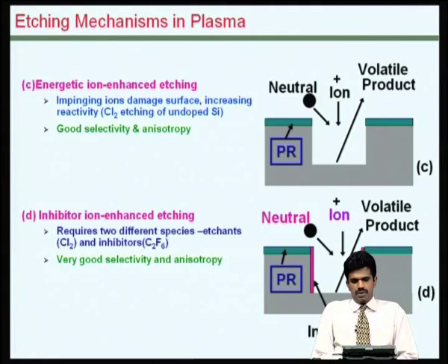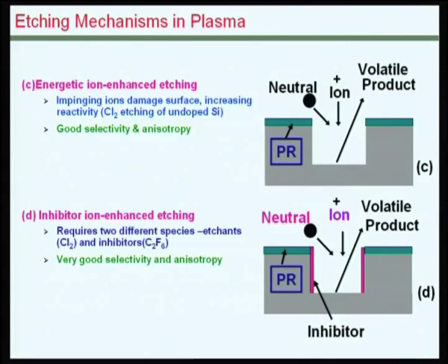Yet it may become a problem when you want to dig deep into the bulk of the wafer. It often requires attaching inhibitors so that we can have a directionality in going deep into the wafer for deep structures with high aspect ratio.